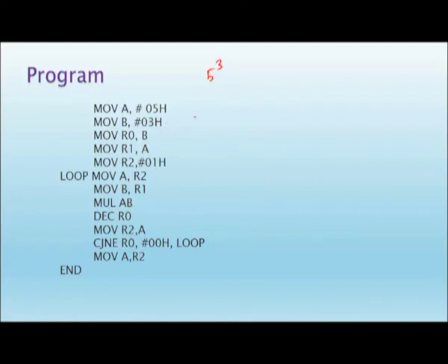So, 5 is loaded in the accumulator, n is loaded in the B register. Okay. For a simple repetition process, I temporarily moved to R0 and R1. The 3 is moved to R0 and accumulator 5 is loaded in R1. The initial process, the number of loops, what it represents: 5 is to be multiplied 3 times, right. That time repeatedly we are using, the counter value sometimes 3 becomes 2, 2 becomes 1, and one more time it will take it. So, to avoid that, I initially multiplied with 1 into 5.